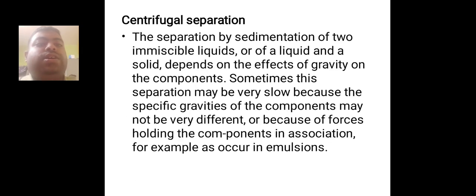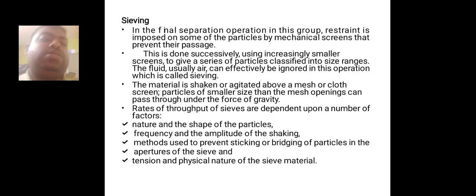Centrifugal separation. The separation by sedimentation of two immiscible liquids or of a liquid and a solid depends on the effect of gravity on the components. Sometimes this separation may be slow because the specific gravities of the components may not be very different or because of the forces holding the components in association, for example, as occurs in emulsions.